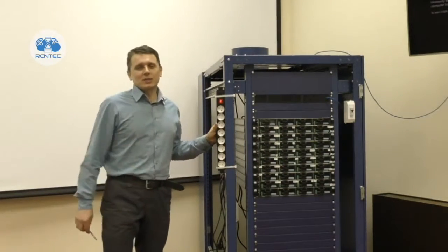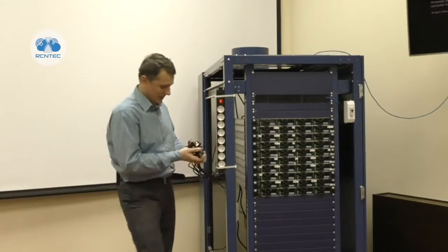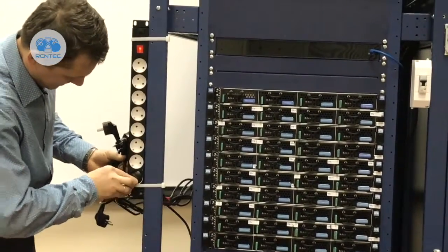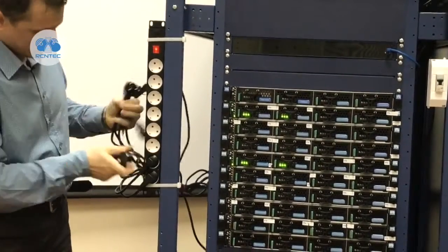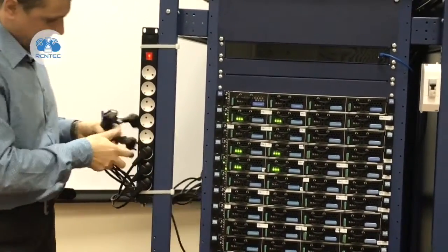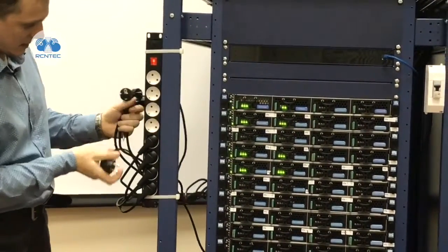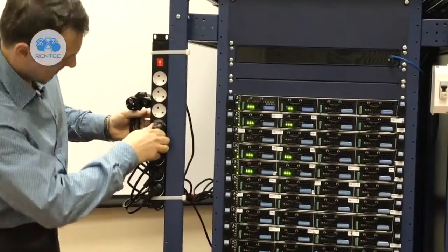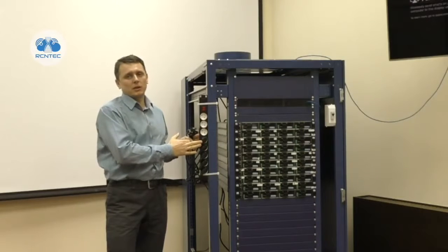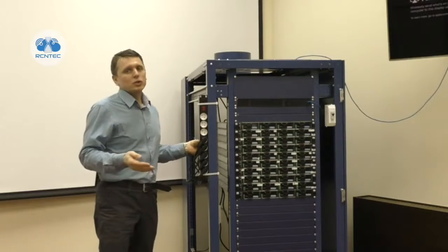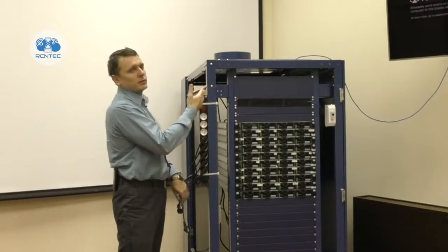As you can see, I've restored the power supply, and now I'll start to connect back consumers one by one. Yes, as soon as I've connected the faulty device, the circuit breaker has triggered again, and again all equipment has been powered off immediately.